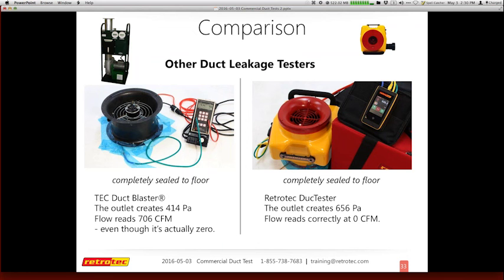So I have some screenshots here of Fantastic automatic testing software. Again, you may be familiar with this as something that you use for your fan operations, or now understand you can also use it for duct testing. It also has a residential side and a commercial application. So there's several things that you're going to enter in terms of the class of the ductwork, the pressure, and a variety of features, and then we'll actually calculate it whether you do it automatically or in a manual type of a mode.